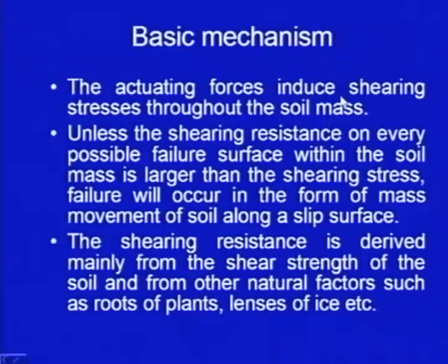Now, we will be talking in terms of shearing stresses. Unless the shearing resistance on every possible failure surface within the soil mass is larger than the shearing stress, failure will occur in the form of mass movement of soil along a slip surface.